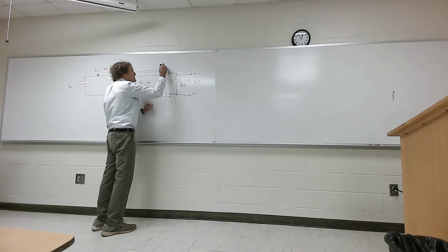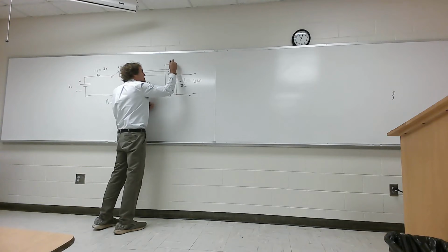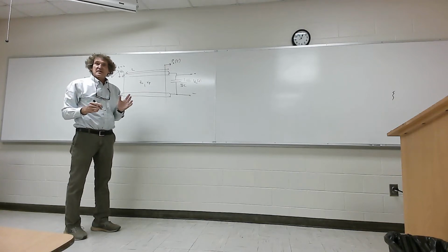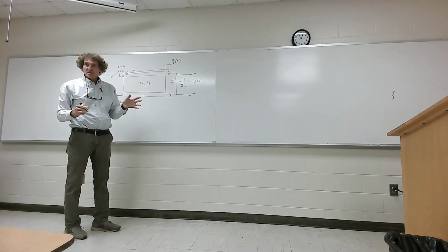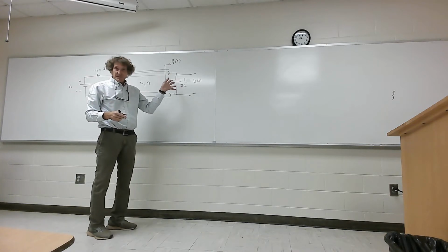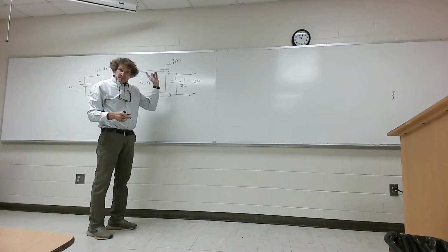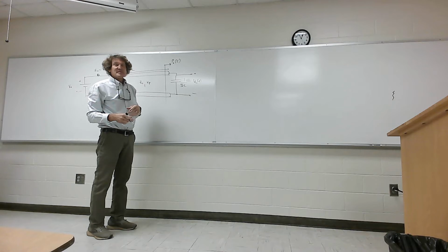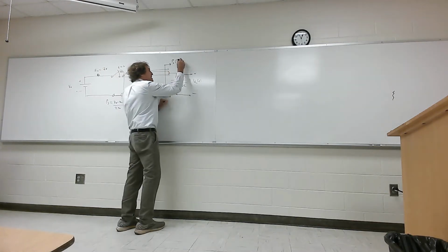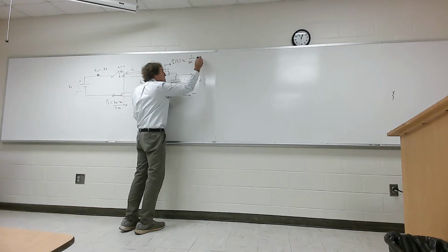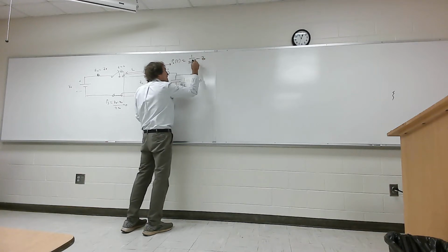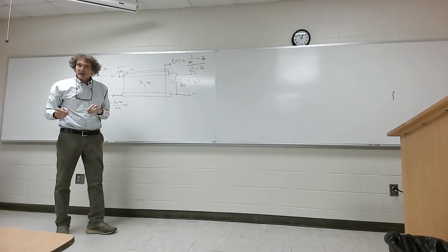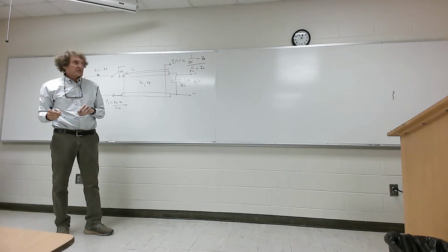Now, the reflection coefficient here, at the load end, will be a function of s. I'm doing it this way because, frankly, it's easier to understand than a complete time domain solution, where I'd have to write the differential equation, C dV/dt equals I, and solve the whole thing, which gets a little tedious. So the reflection coefficient here is the impedance I'm going into, 1 over sC, minus the impedance I came from, Z0, over the impedance I'm going into, plus Z0. Do you all agree with that? Okay? We're talking about the impedance of the capacitor being 1 over sC.